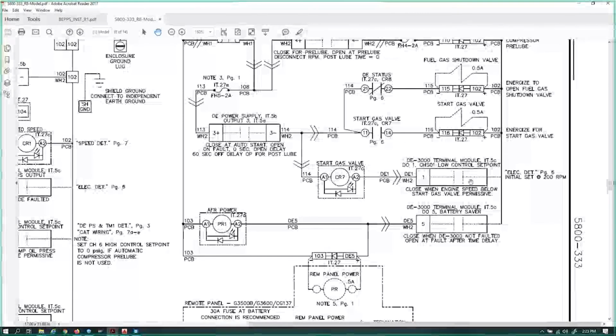The first thing we're going to do is look and see how the low control set point is configured through the menu, because that's the quickest thing we can do. If it looks like it's right, the second thing we're going to do is extract the program. Too often, what I find is that somebody has gone into the program and messed with it, and they've actually turned off the checkbox that allows that digital output to turn on.